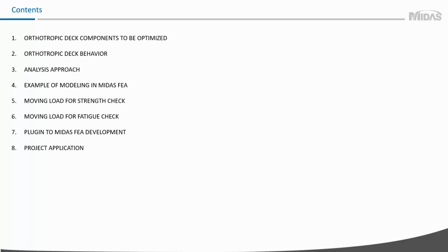I will describe the algorithm for how to effectively perform analysis using the finite element method approach, and how to apply moving load on the deck. I'll explain how you can use programming skills for developing your own plugins for Midas FEA. This will be explained based on the moving load auto generation to make the working process more effective. And at the end of the webinar, I will give you an example of how the described background can be used in real practice.